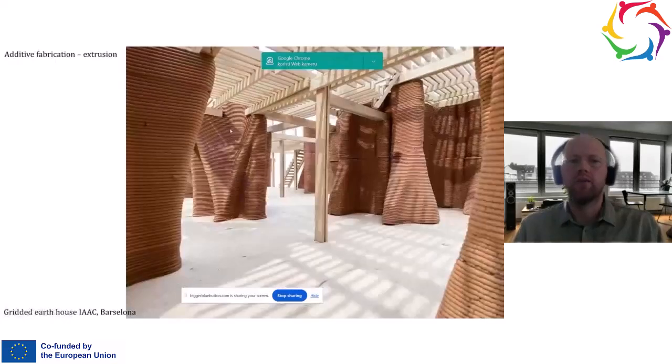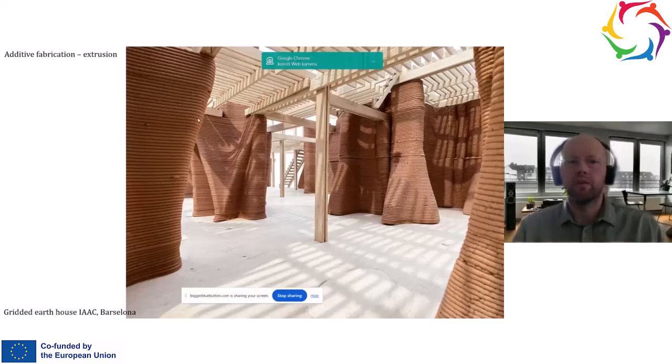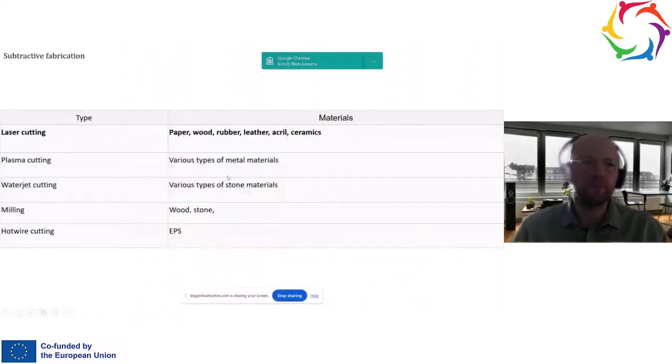The reason is that if you make a large scale 3D print with concrete or clay, you should avoid sharp corners, because in the places where corners meet, the material can be very sensitive, and cracks can appear. So it is better to start designing such a structure that is already curved, so you don't have corners. Even if you have to place some corners, you will make a round or fillet in that place.